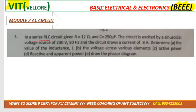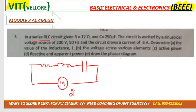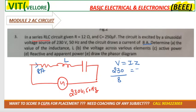See, in a series RLC circuit, the circuit is excited by a 30 volt 50 hertz supply, right? Current is 8 ampere. Calculate L. So V is equal to I Z, 30. Current is 8, so you can get Z. Z is equal to root of R squared plus (XL minus XC) whole square.